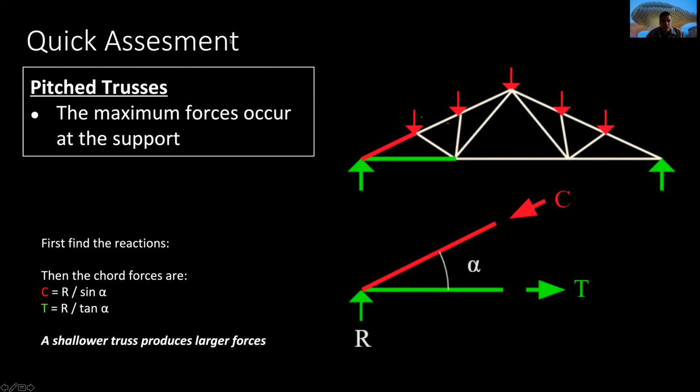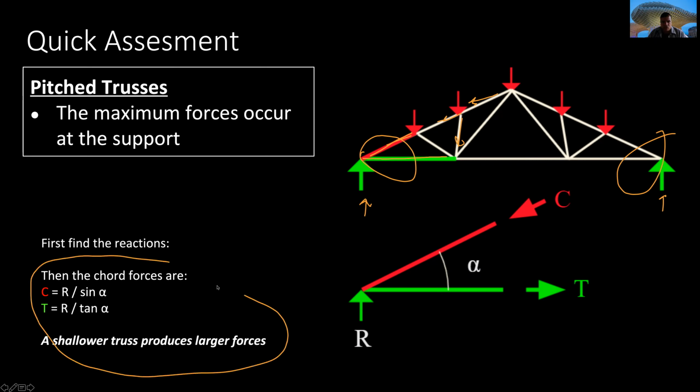I mean, if this particular truss is supporting weights in the nodes that are there, because you have a roof, for example, on the top of this truss, well, all those forces will be transmitted, and all the members are in compression or in tension, to this point, because that is the point where you have the columns or reactions that are supporting this truss. Well, the member in red and the member in green will be the ones that will be supporting more weight, and we can calculate the forces using those